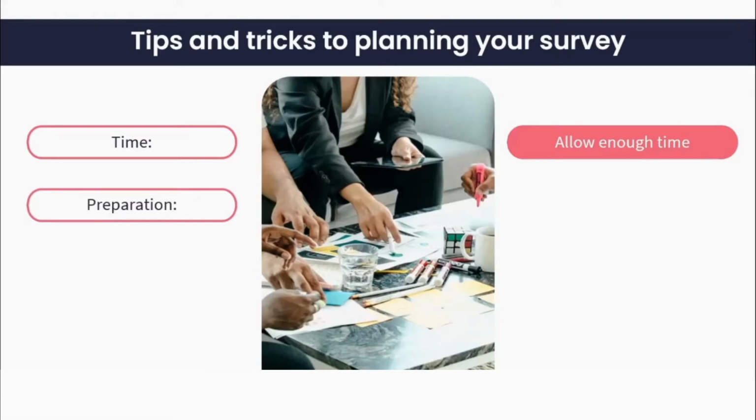Secondly, you want to prepare before you conduct the site survey. Make sure that you know how to get to the site, and how to access the space if the client is not going to be there, obviously. Before I conduct any site survey, I also make sure that I have all the relevant detail relating to that project printed beforehand. You may have an existing plan from the owner or landlord. Print that off and take that with you. You may have an email from the client on how to access that space. Print that off and take that with you as well.